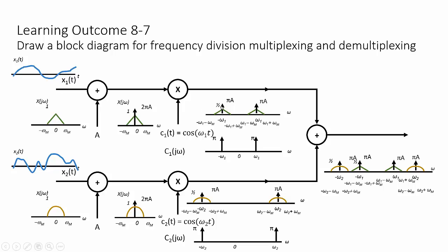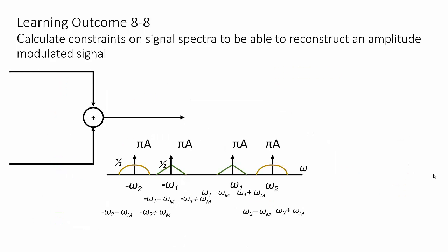And if we did it right, we will set things up so that this spectrum will not interfere with this spectrum, and everything shares nicely. This is the process called multiplexing, specifically frequency division multiplexing. Look at our variable, it's frequency. We're putting multiple signals in frequency. So now let's take a look at this a little bit closer.